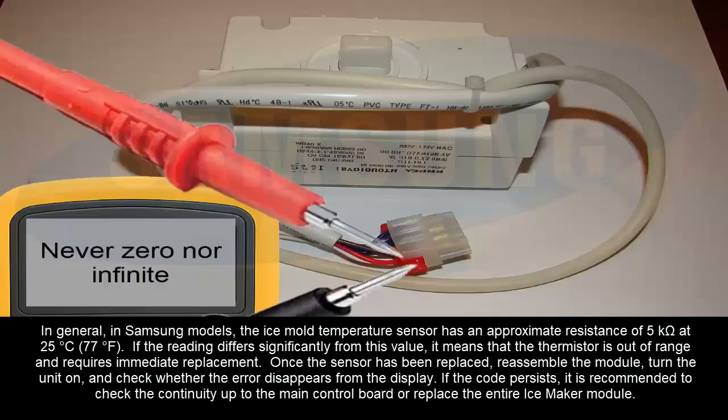In general, in Samsung models, the ice mold temperature sensor has an approximate resistance of 5 kiloohms at 25 degrees Celsius or 77 degrees Fahrenheit. If the reading differs significantly from this value, it means that the thermistor is out of range and requires immediate replacement. Once the sensor has been replaced, reassemble the module, turn the unit on, and check whether the error disappears from the display. If the code persists, it's recommended to check the continuity up to the main control board or replace the entire ice maker module.